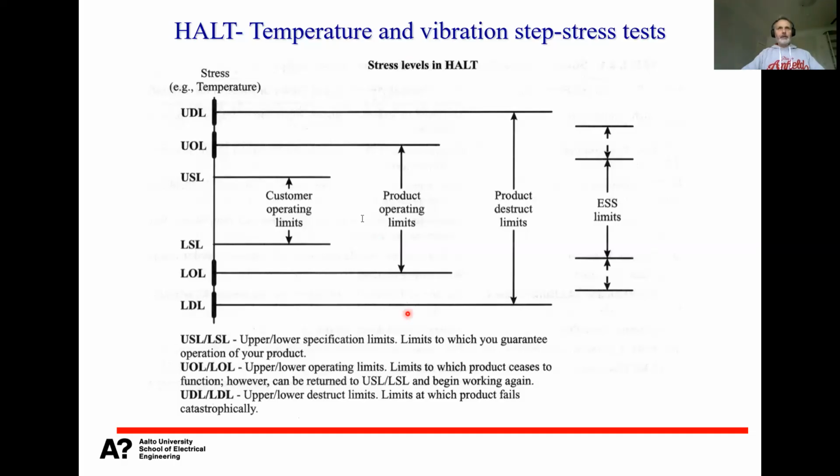Could there be any other method to perform the test apart from temperature, vibration, for example, voltage or current? Yes. So basically, what I'm showing now is the standard way, the classical way of doing HALT. And if you put HALT into Google, you end up with HALT chambers, which the companies are selling, and they are practically always a combination of temperature and vibration. But in principle, you can use whatever stressing conditions with the same idea behind.